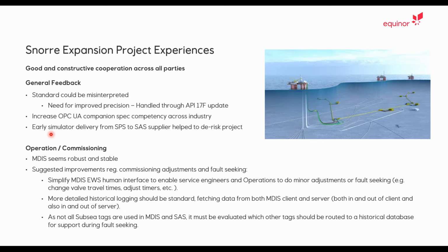We also feel that more detailed historical data logging should be standard. And we also see that not all subsea tags are used in MDIS and SAS. So we must be better in evaluating which tags should, let's say, rather be routed to a historical database for support during fault seeking.